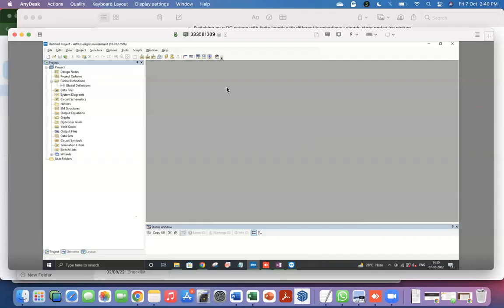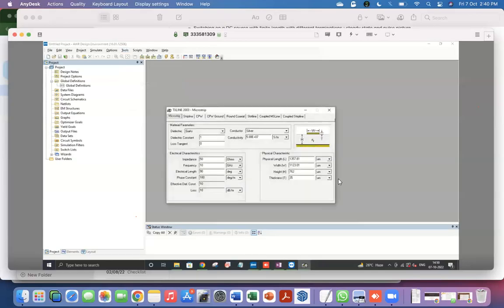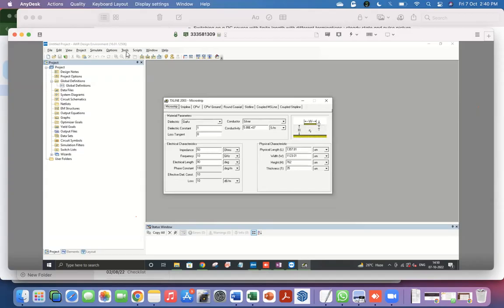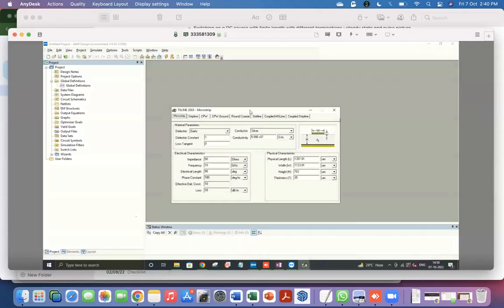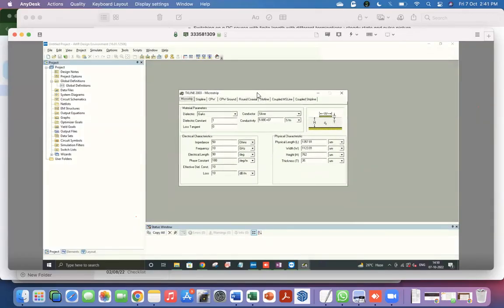Okay, so last time we were discussing the different types of transmission lines, and we looked at the coaxial transmission line in some detail. And we were looking at this tool, which you can access from inside microwave office in the tools menu called TX Line. It's actually a separate program, and you can find it somewhere in the installation files, and you can run it separately, independent of microwave office as well.